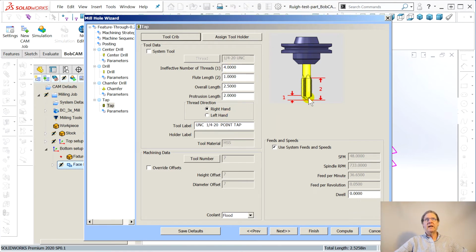So this is something I'd worry about. Well, are they going to the tip? Are they going to go too far? Do they define the drill by the tip of the drill as 0.38? Then it won't be deep enough, because that's not the way Solidworks works. I think it goes by the flank of the cylinder, not the little extension of the 118-degree tip. That would be interesting.